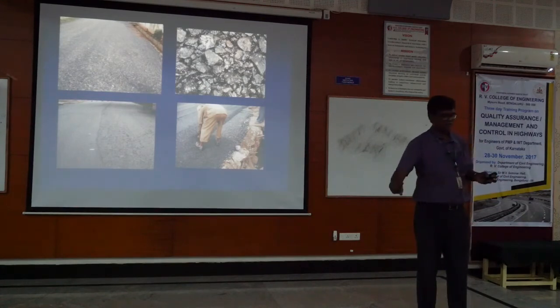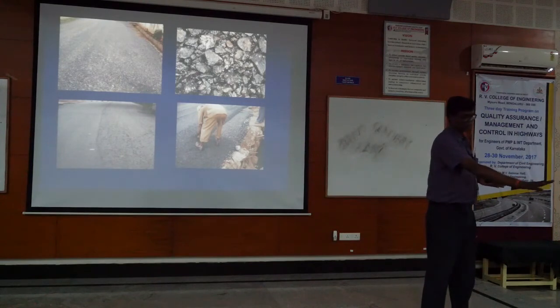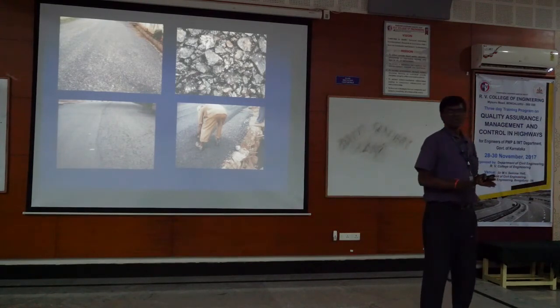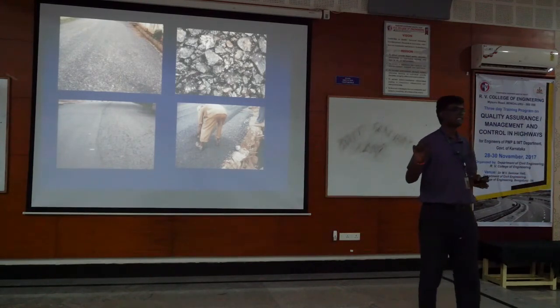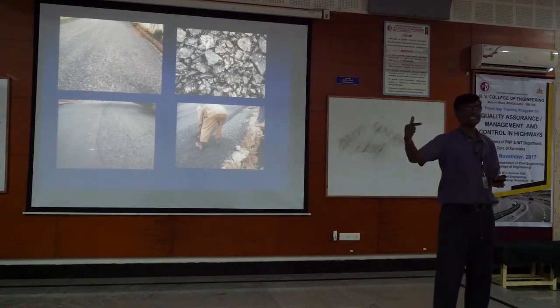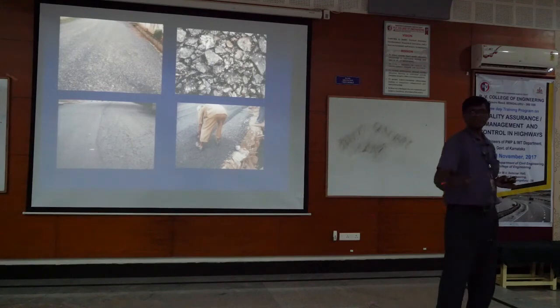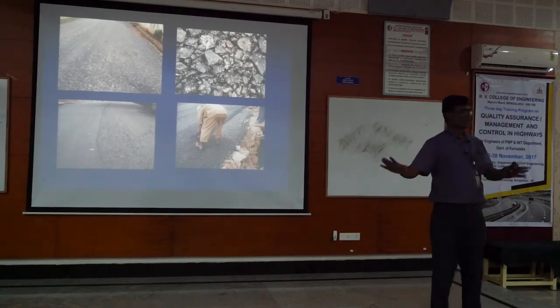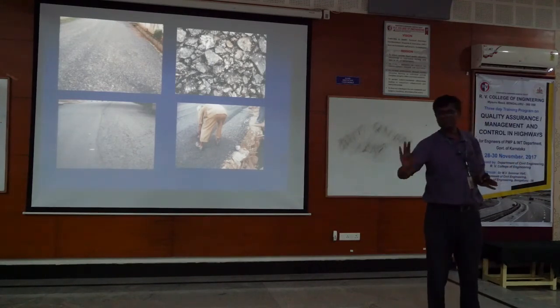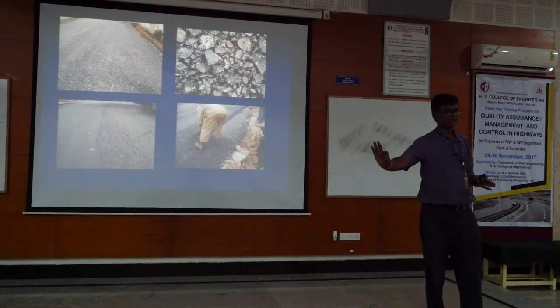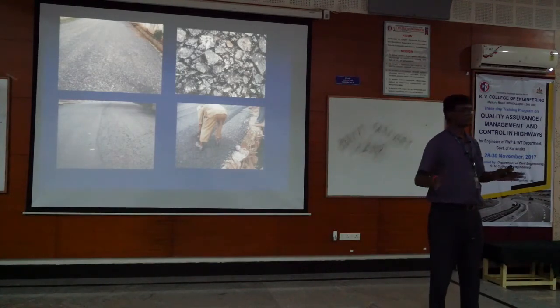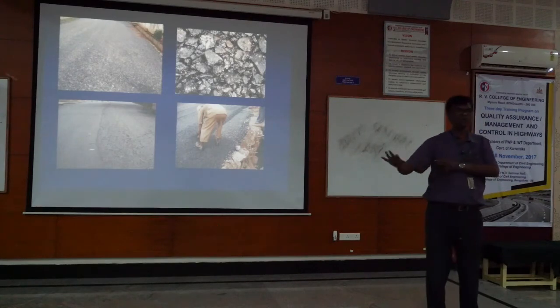You would have done the initial mock-up for that material, for that number of passes using that machine, so I would have known the density achieved. Unless I change my quarry, my mix ingredients, or my compactor, I know that this many passes give this density. So we should go by that.